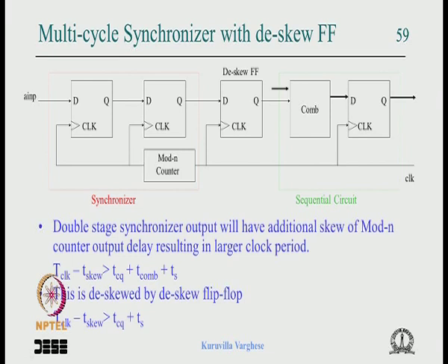So that is what we looked at in the last class. I have repeated it because it's important, and it should get into your mind very clearly. This is a kind of standard solution; people almost treat it as a thumb rule. Wherever they see an asynchronous input, they put 2 flip flops in a chain, sometimes they put 3 flip flops. We will see why 3 flip flops.